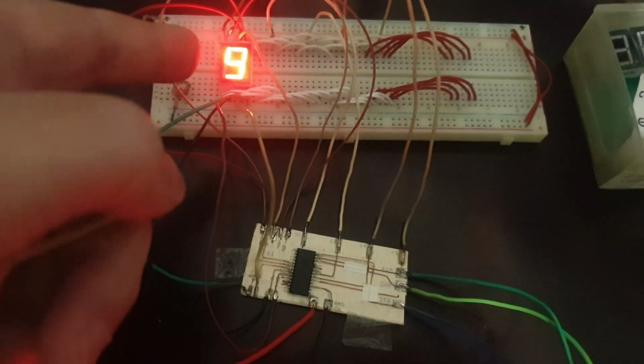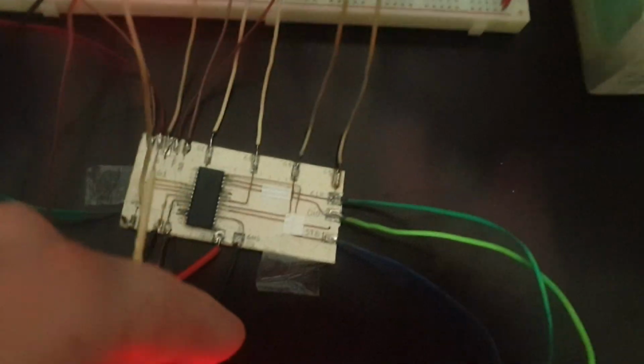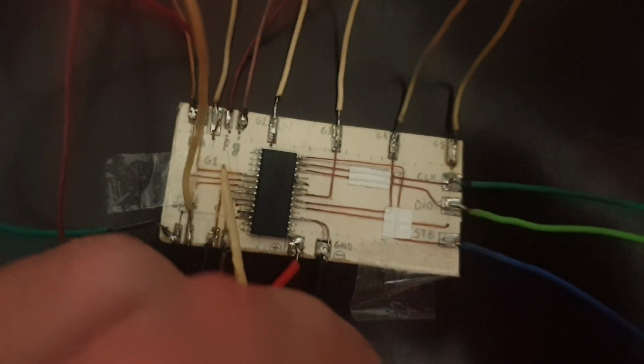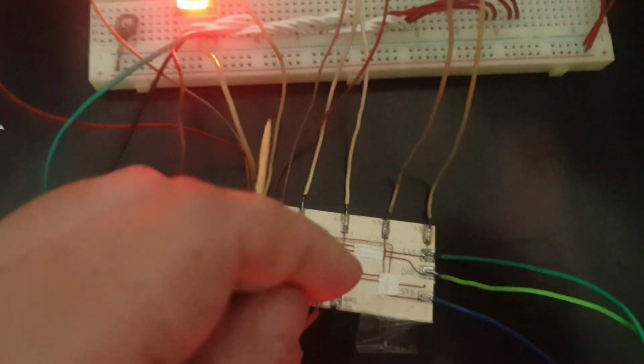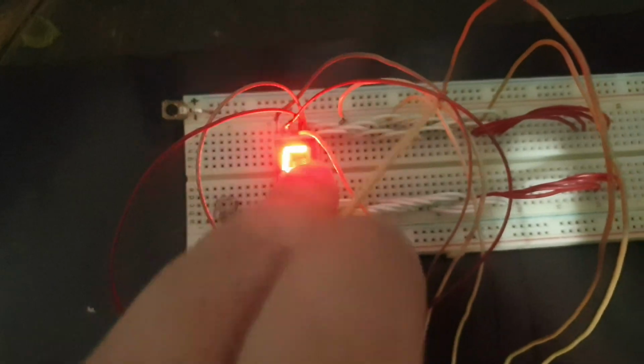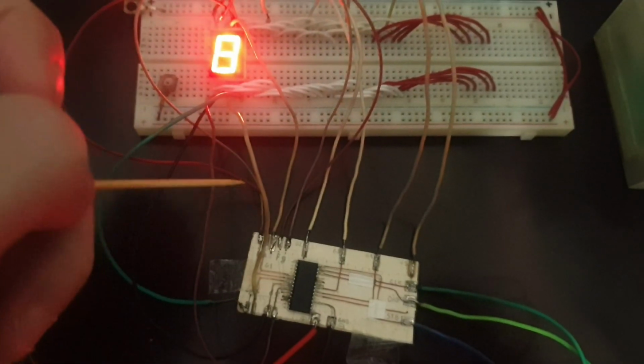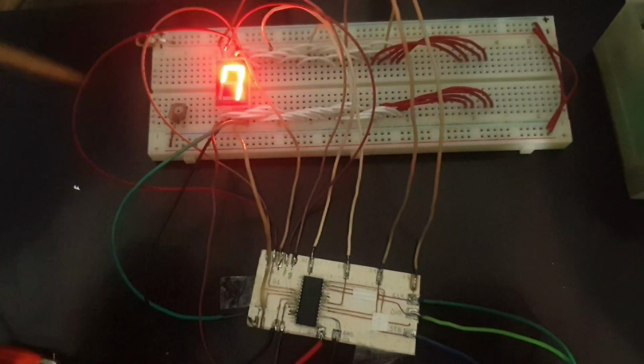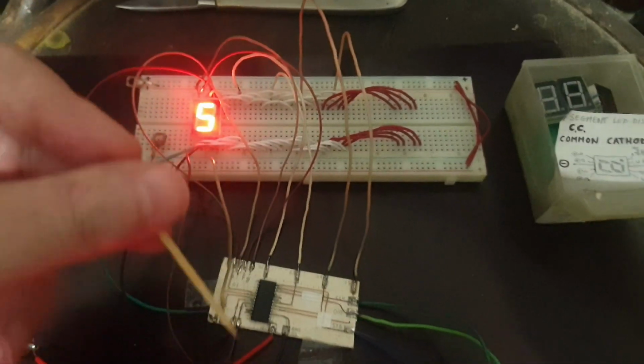Right now the program is driving only one single display. You can barely see it here, but it's in the middle. This one is actually saying G1, which means grid 1 is this one in the middle, and this line, if you're following it, is right in the middle of the display. The chip is sending a positive signal through all the segment lines, through here and through these long wires to all the segments. So right now I'm presenting only one single display running with the code from Arduino through this chip.